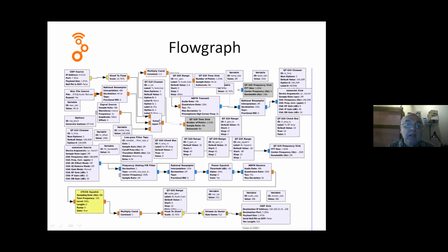So normally the switch is in the voice position, and there's nothing coming over the network. So there's no data going to the modulator, no data going to the resampler, no data going to the sink block. So the driver puts it into receive mode. That's what happens as long as there's no data to transmit.